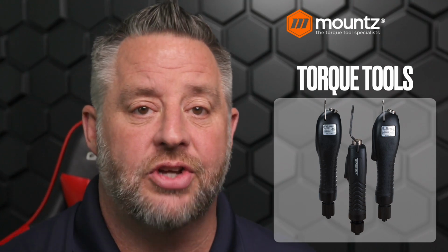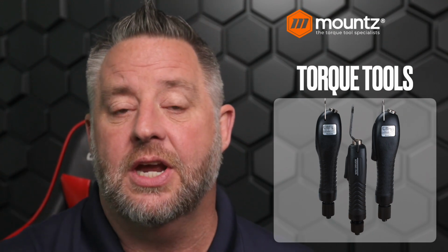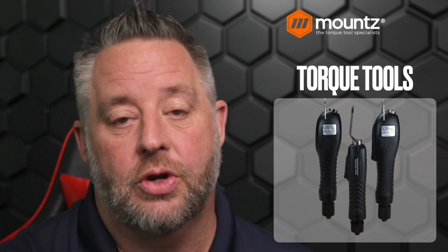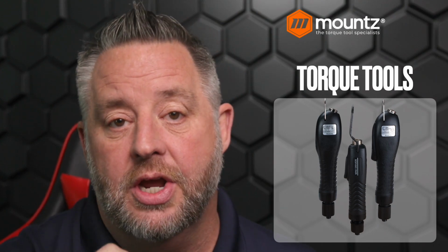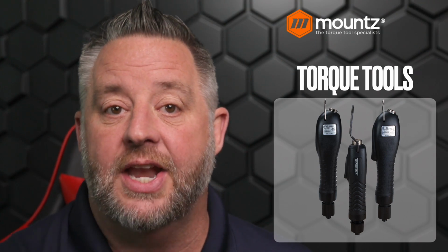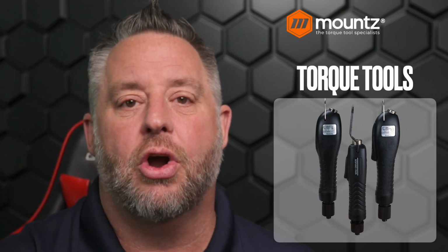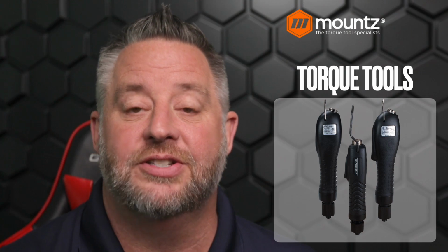And so you may have a really soft gasketed type of joint that may see some relaxation after the initial torque has been achieved. So we have a screwdriver that can provide a double hit mode where it torques out twice. So it'll click, click. And that second click will give you a better torque on the compression of that gasket. We have different drivers that have different RPMs that allow you to adjust those RPMs, that have a soft stop feature, a soft start feature. And again, those are all determined by the application, but a very, very popular choice for assembly as well.